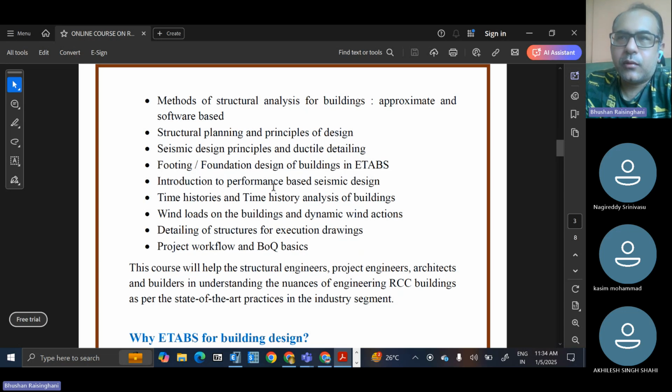The fixed depth below the ground should be modeled with horizontal and vertical springs, which is a very detailed aspect, and geotech engineer approval is necessary for all these parameters. A structural engineer cannot directly do it. For vertical springs it is okay, but for horizontal springs you cannot just decide by yourself what is to be done.